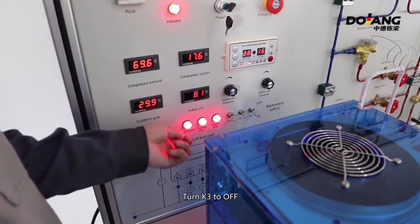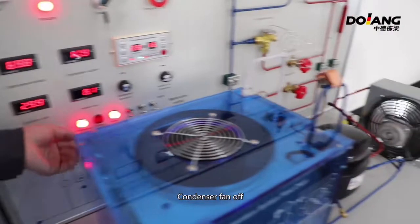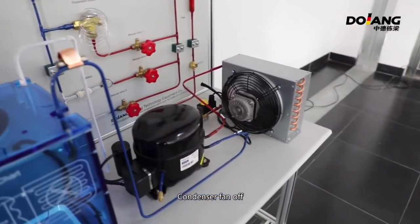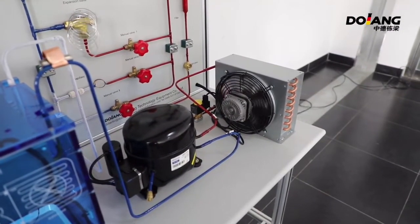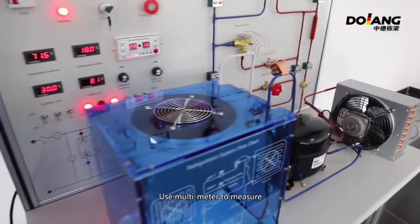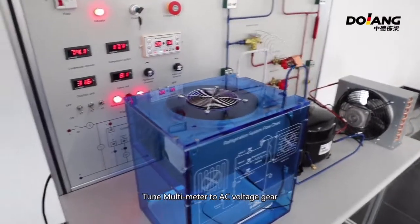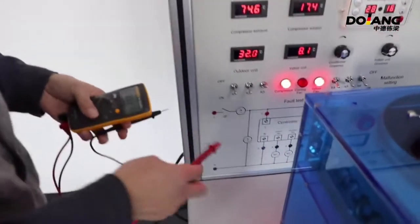Now do the third fault experiment. Turn K3 to off. Condenser fan off. Use a multimeter to measure. Turn the multimeter to AC voltage gear.